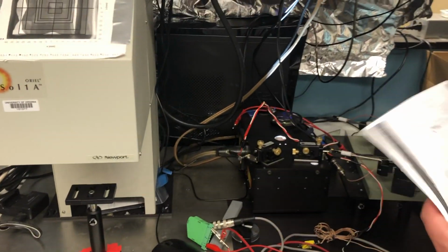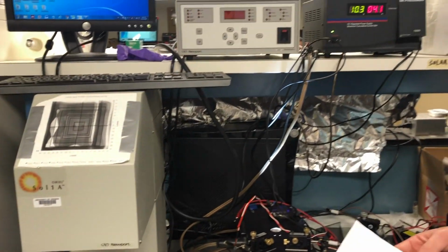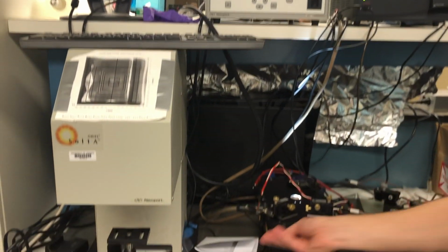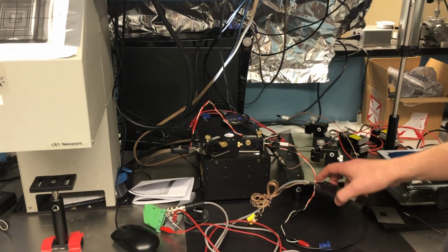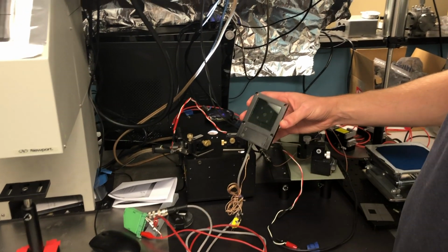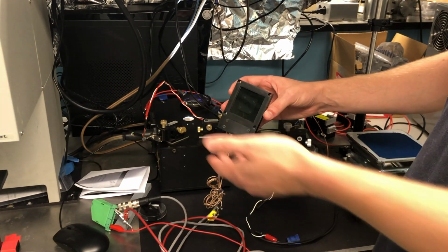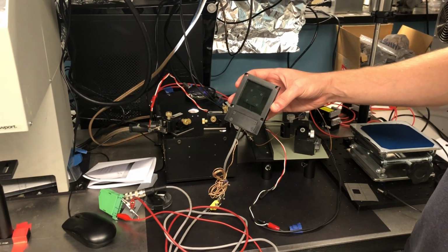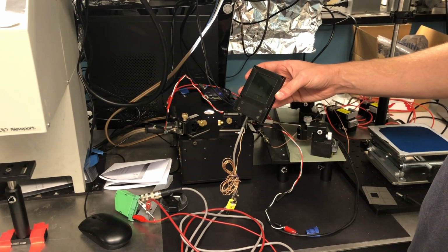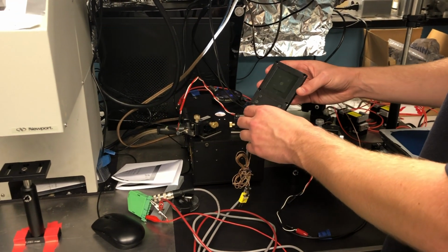So why do you need that? Because these lamps can kind of drift over time, the voltage can change as they degrade, the current intensity could drop. You're going to want to make sure that you're accurate so that whatever data you're reporting isn't going to be far off. So the reference cell is just a really stable solar cell. You'll notice it wasn't very efficient. It's only about 4% efficient. But it's useful to have so that you can make sure your data isn't totally bogus.